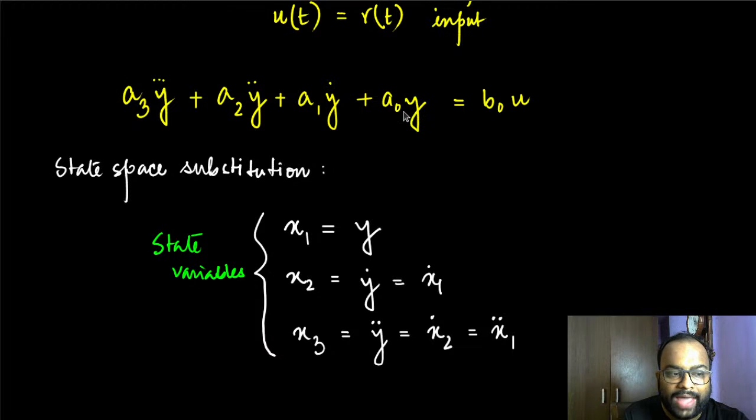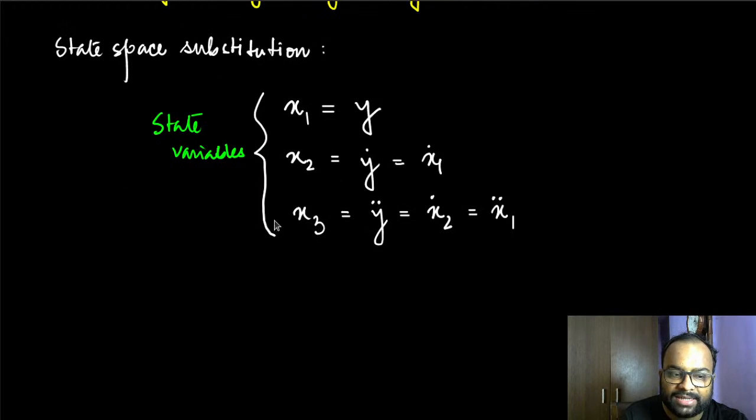So we have certain mechanical variables associated with the differential equation, namely displacement, velocity, acceleration, and jerk. And you see that the state variables represent some of them already. x1 represents the displacement, x2 represents the velocity, x3 represents the acceleration. So if you think about it, the state variables help us describe certain internal behavior of the system.